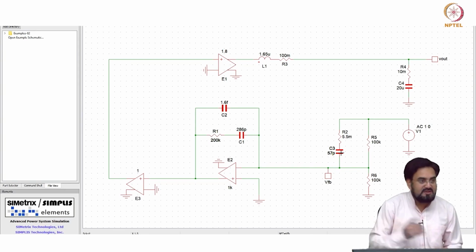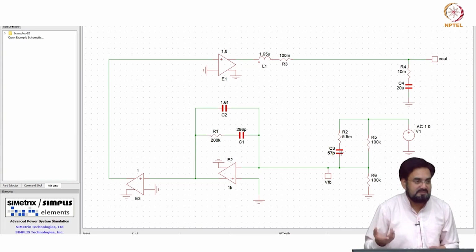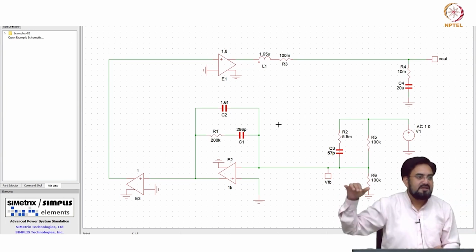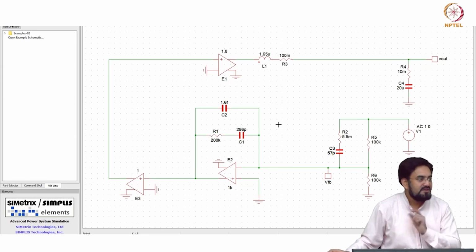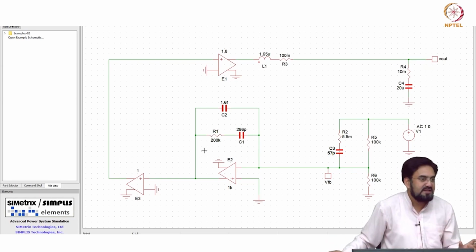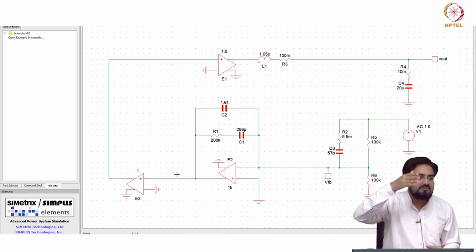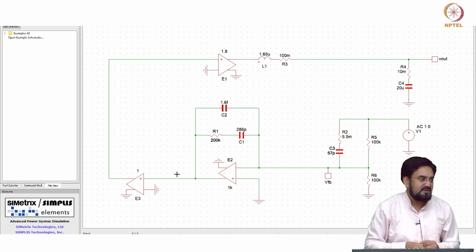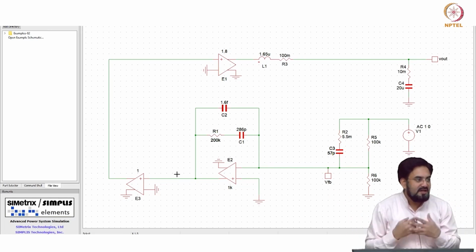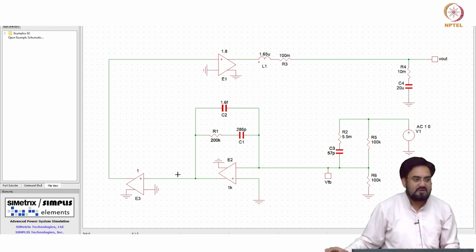If I keep moving the 0 inside, that means I have to add more caps, so area is one problem. The other problem is, if you look at the mid band gain, we are reducing it. So your settling will be much slower, because as I mentioned, you want your loop gain to look more like first order, but moving inside means you are getting a flat gain in between and your settling will slow down, and we can see that in simulation.